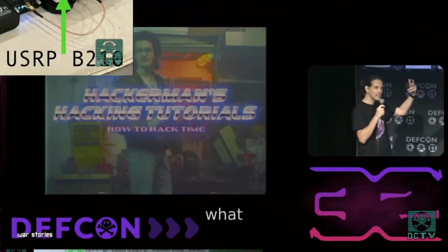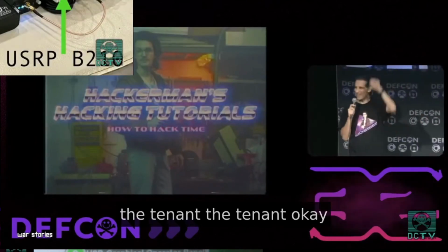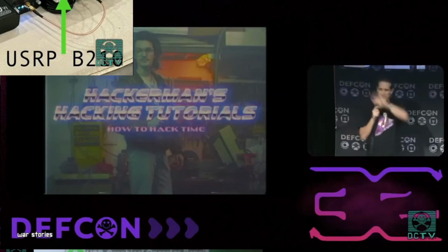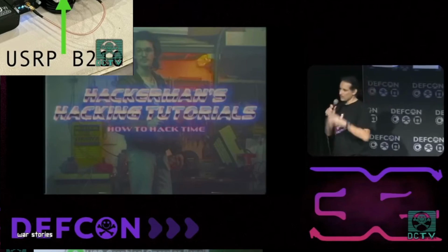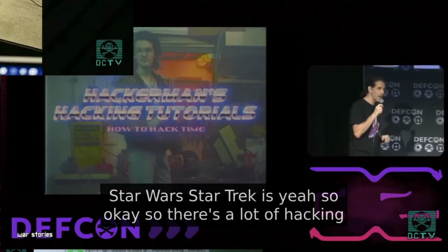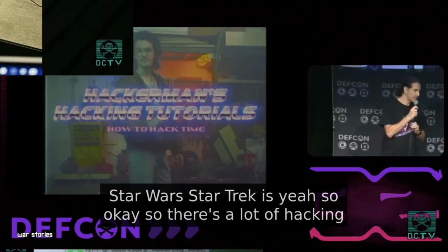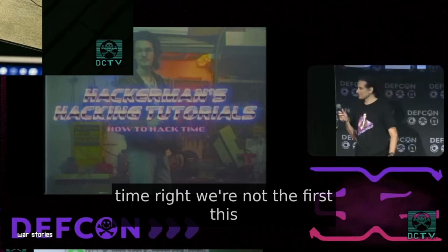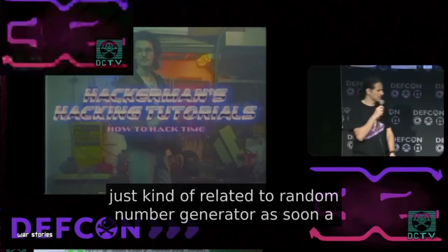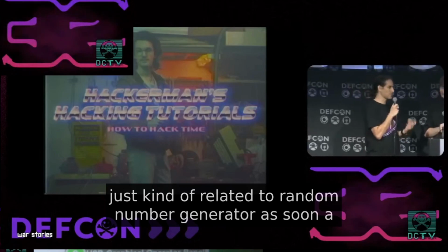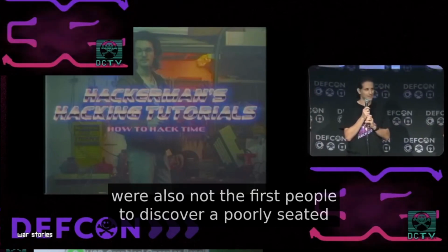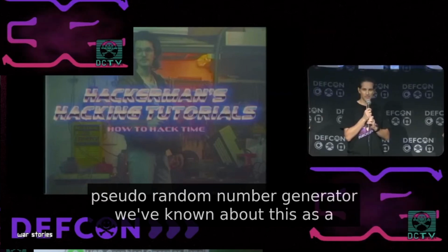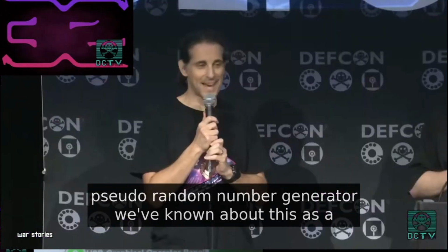Here's the physical setup. This is the receiving side. Lens to capture light, into a photodiode, into the amp, into the USRP B210, into the computer. If you see this outside of your window, it is super sketchy. Maybe shut the blinds, call the police. But once you actually point this laser at a computer, now there are some big challenges here. Actually performing alignment is very, very, very challenging.